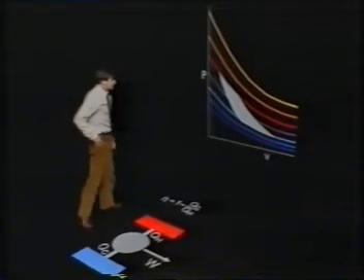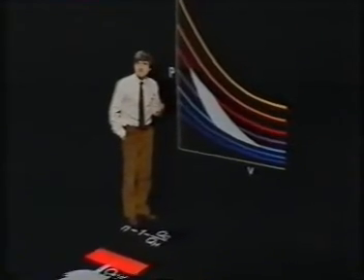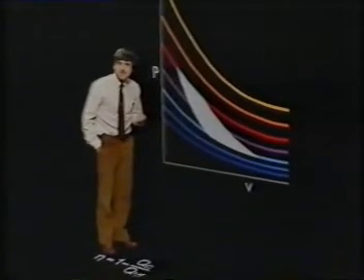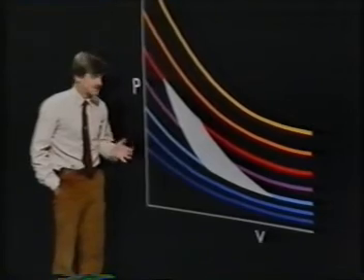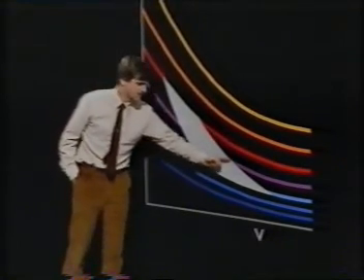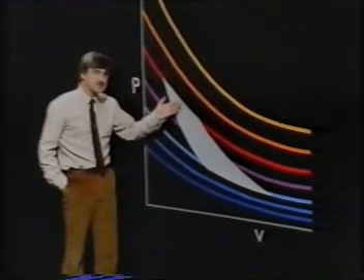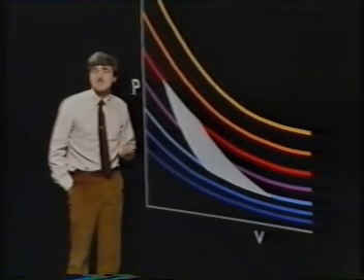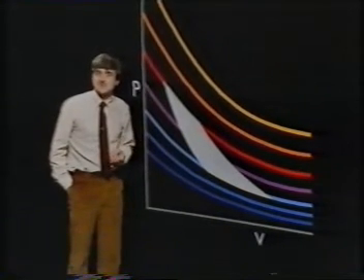Moreover, any temperature change which the working fluid undergoes must occur while the working fluid is in isolation from the environment, that is, during adiabatic processes. The heat transfers have to occur isothermally and, in the limit, with a zero temperature difference. That's what we mean by a reversible process.